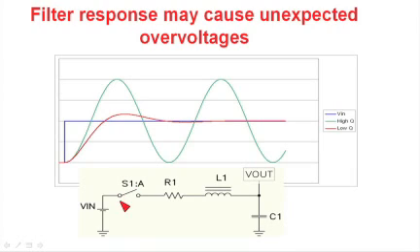We have a voltage source that's connected to our system through a switch, and then we have this resistance and inductance here, and those would represent the resistance and inductance of a cable, or they might represent an intended filter component, where the R is just simply the winding resistance of the inductor. And here you can see what happens to the system as we apply an abrupt voltage step to it.